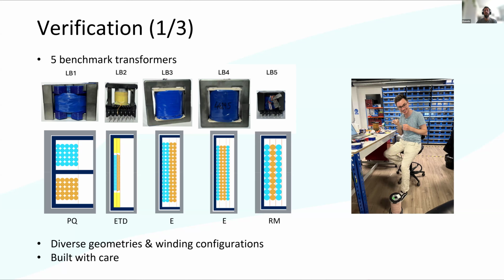Okay. And we have a very good question, which is, what about the leakage inductance of U or UR cores, especially when the primary and secondary windings are located on different ferrite poles? Yeah, then you need a different modeling approach. The modeling approach of the Quasi 3D leakage inductance model is based on when you have all the windings on one leg.